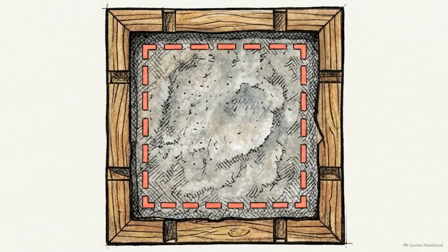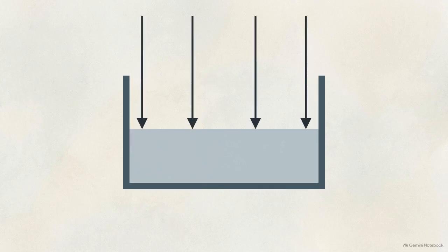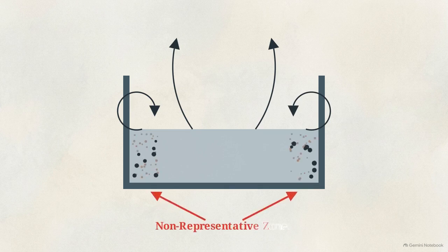Within that extraction phase lies one of the most critical physical limitations of the standard. You cannot drill a core from just anywhere on the panel. Extraction locations are strictly controlled. This diagram illustrates the mechanics of the edge effect. As shotcrete is applied, high-velocity air and materials strike the formed edge. This interrupts standard airflow, creating turbulence and trapping defects, specifically sand lenses and voids, near the panel's sides.